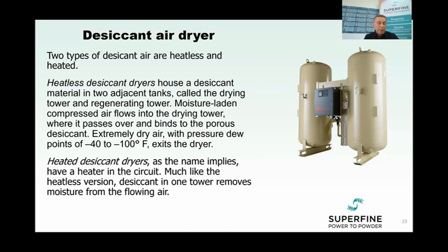When weighing the virtues of heatless versus heated desiccant air dryers, keep in mind economics. The cost of generating compressed air can be sizable, and heatless dryers use about 50% more compressed air than heated ones for regeneration. On the other hand, heaters can require a lot of electricity. Thus, users should review the specifics of the application to decide which type costs less to operate.